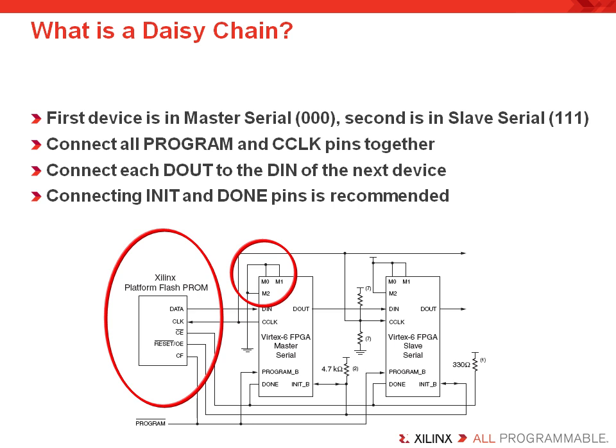We have also connected the DONE pins together. Tying the DONE pins together prevents the system from coming out of configuration until all of the FPGAs are configured properly. Note that you should check your configuration user guide and the datasheet to determine the proper pull-up resistors necessary for this kind of system.